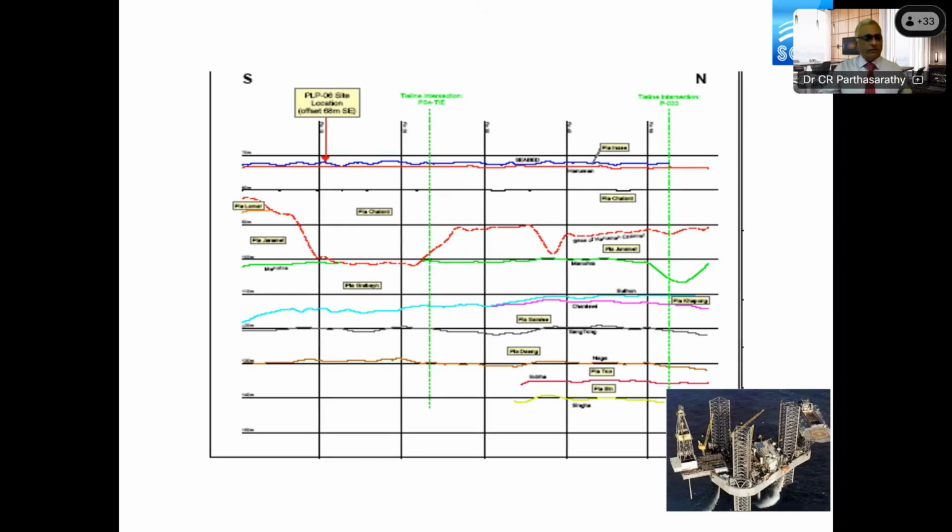So this is a channel feature. Usually the survey is performed with a dedicated drill ship. Many times the planning is such that you don't have the rigs available, but the rig has to move to the location. In such a case, it's the last resort. The rig will be moved to the location. It will be soft pinned, that means it's just touching the seabed. And then you utilize the drilling rig of the jackup barge to do the borehole and collect the samples.